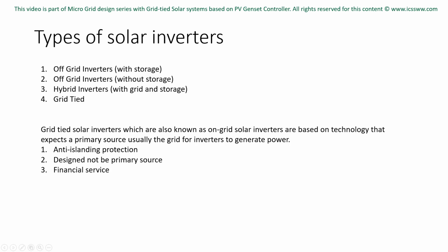Grid is assumed abnormal in case of overvoltage, undervoltage, overfrequency and underfrequency. All inverters based on this technology by standard cannot generate in case of grid blackout, so the electric utility personnel can conduct maintenance activities on grid side.